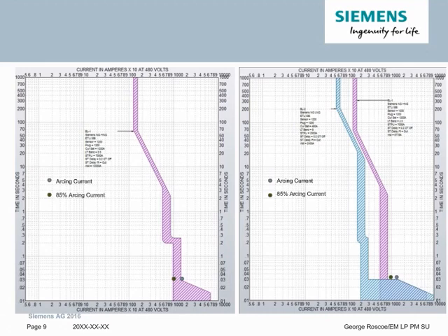The image on the left shows the normal mode of a 1200 amp circuit breaker, and during the arc flash study, the 2 dots show it was found the arcing current was around 10,000 amps, meaning normal settings were above or at the arcing current, meaning the settings would need to be changed to comply with 2017 NEC 240.87.